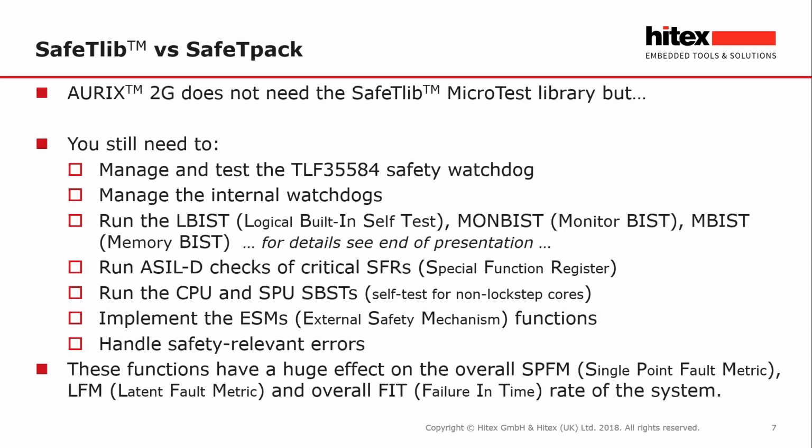On TC3XX, you still need to do an awful lot of preparatory work before you can run a safety application. So you have to manage and test the TLF 35584 Safety Watchdog chip. This is the combined power regulator and safety monitor. You've got to manage the internal watchdogs.